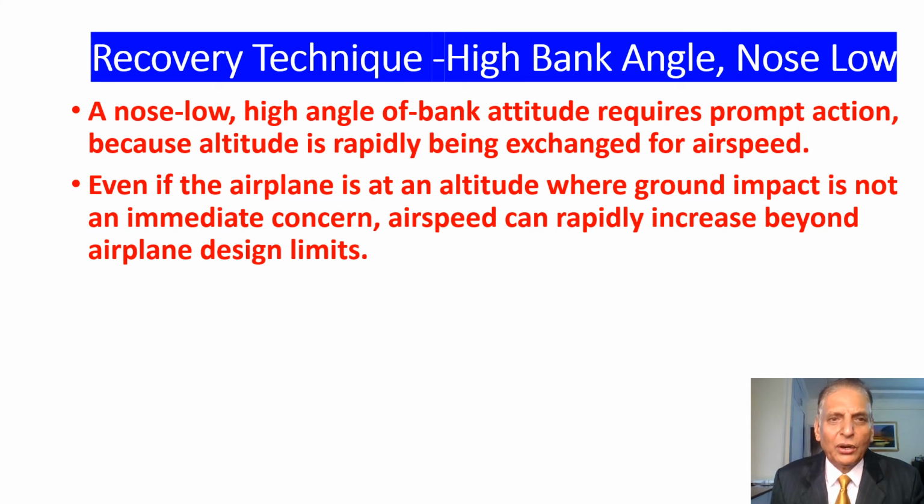A nose low high angle of bank attitude requires prompt action because altitude is rapidly being exchanged for airspeed. Even if the airplane is at an altitude where ground impact is not an immediate concern, airspeed can rapidly increase beyond airplane design limits.